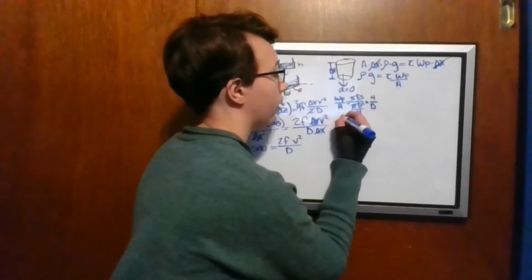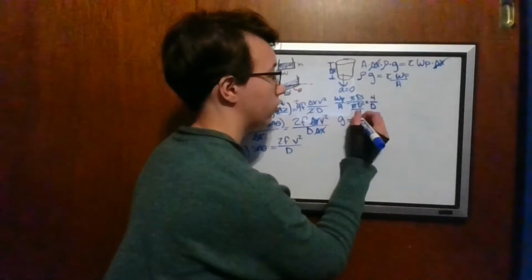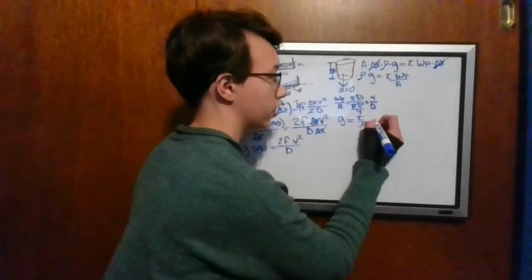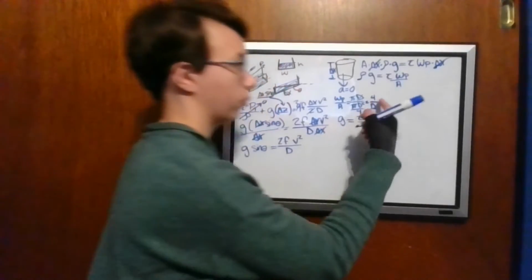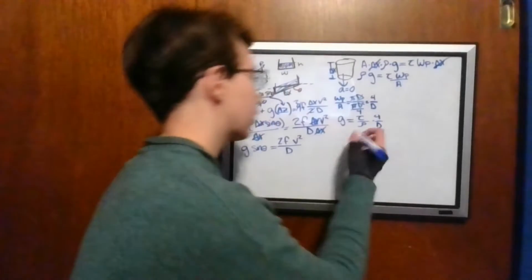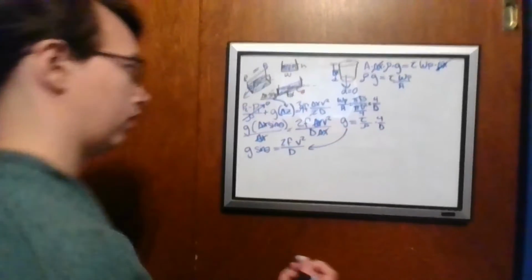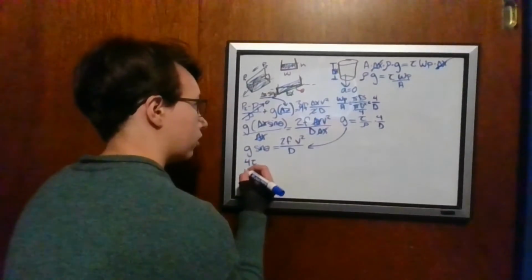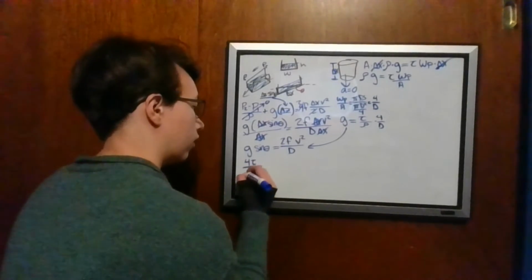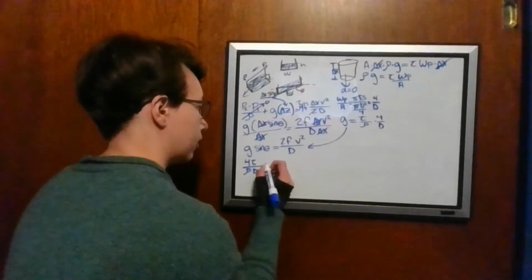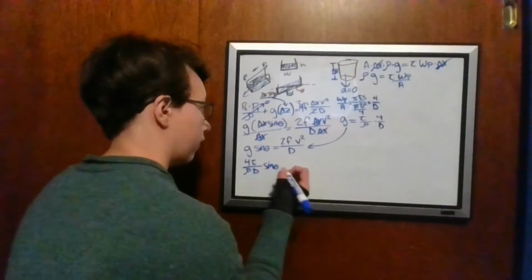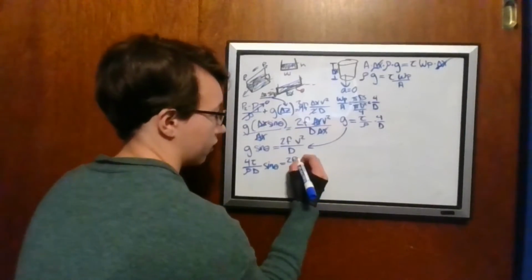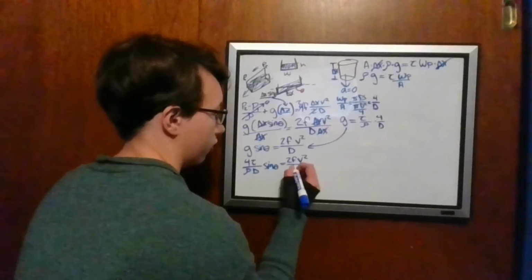So we have that our acceleration due to gravity is going to be equal to the shear stress over the density times this wetted perimeter over area ratio, which is 4 over d, which we found here. So from here, we're going to take this and plug it in down here. So here we've got that 4 times the shear stress over density times diameter times sine of theta is equal to 2 times the fanning friction factor times velocity squared over d.